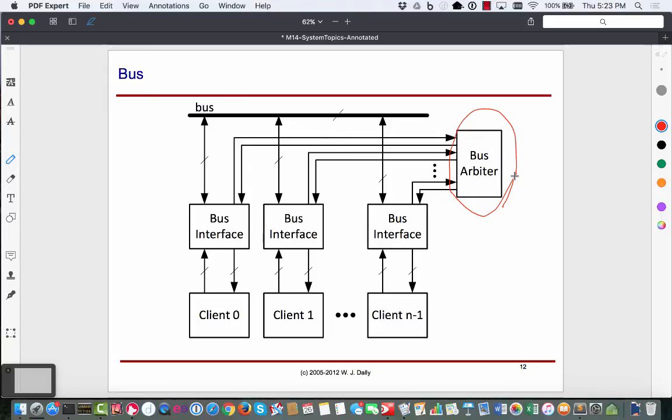A tri-state buffer, maybe? Tri-state buffer, exactly, a bi-directional tri-state buffer. So you can do some magic out there, or a pair of multiplexers. Essentially at select points, I can create switches, and when I open the switch, my bus segments into two. Okay? So we can do those kind of games. I can stick with the bus structure and start permitting multiple transactions going on at the same time.